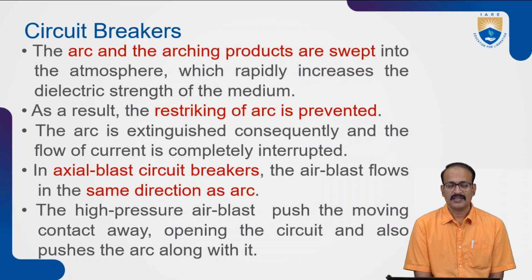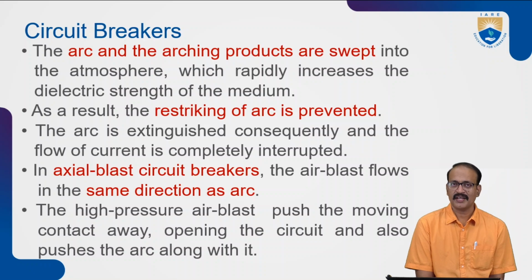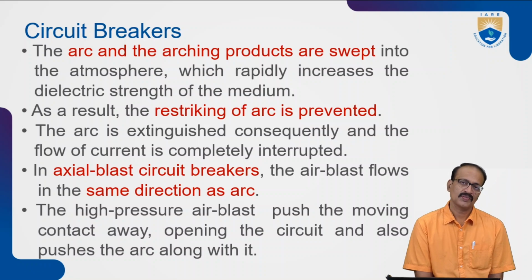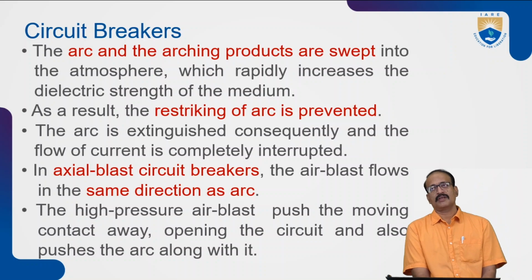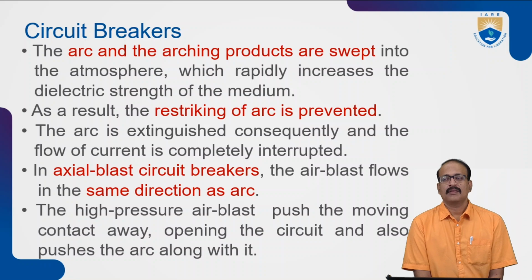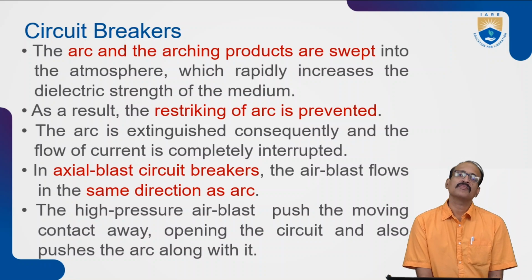In the starting case, there was sufficient dielectric strength and also the distance was small. The arc started and it continued even after the distance became larger, because of the ionized particles.